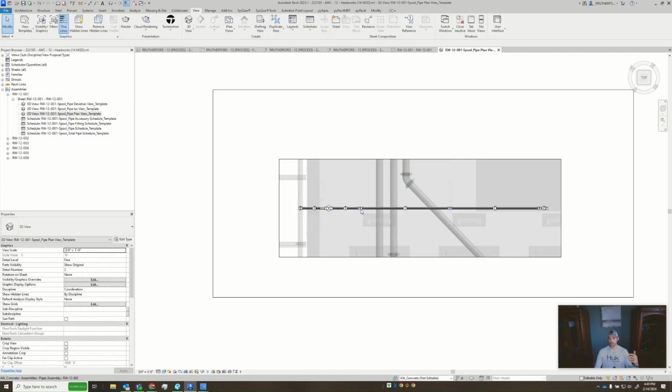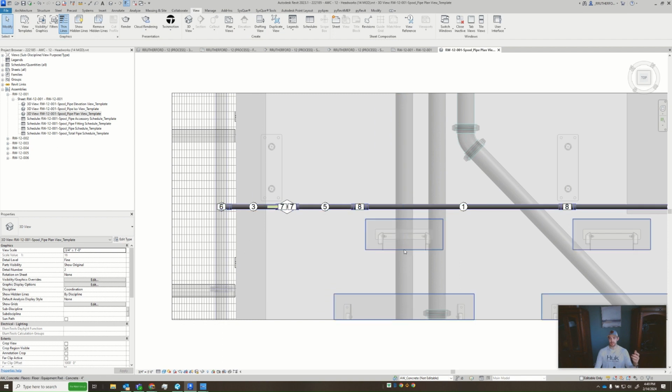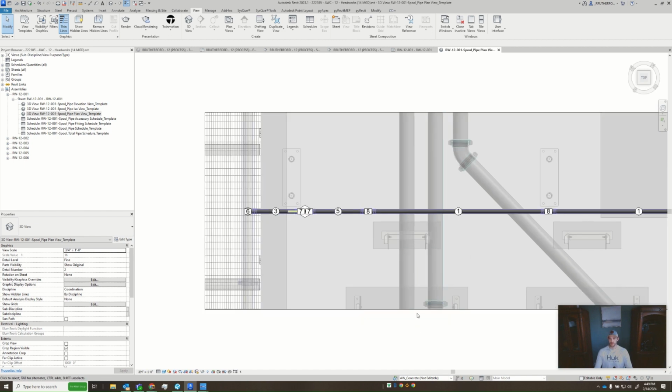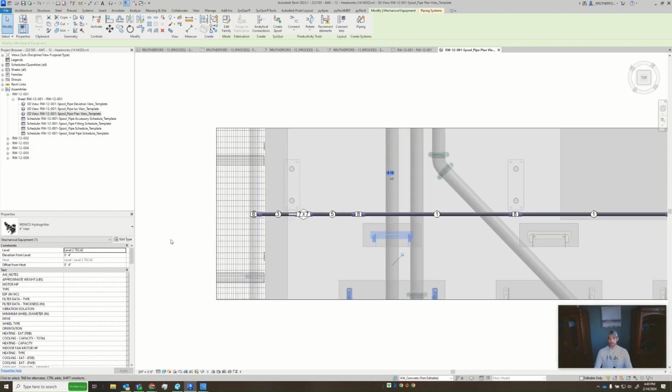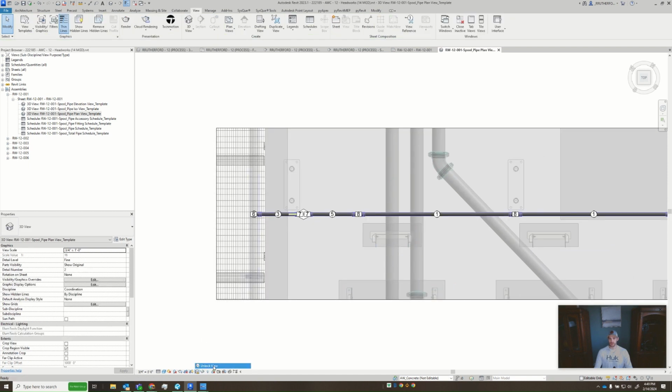For instance, when we get to these T's, I'll try and reference the center line of this equipment, because the center line on that equipment is very easy to see visually on the equipment. They can line up, but also the edge of these pads. But for now, we'll just use the center line of this equipment. That being said, I can only see a little bit of this equipment. So in this case, I'm going to go hit unlock.